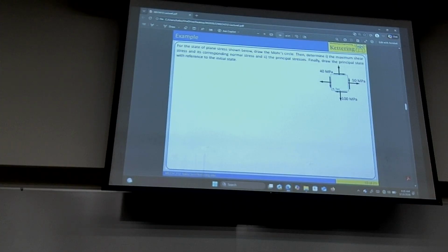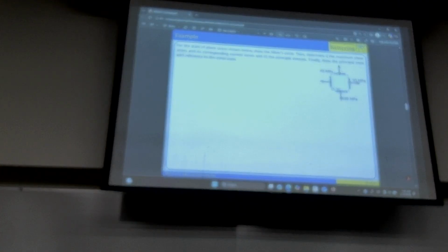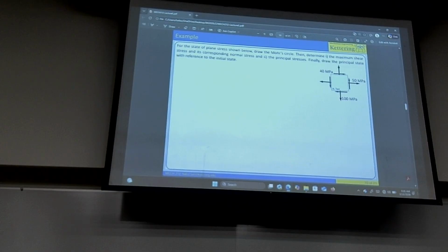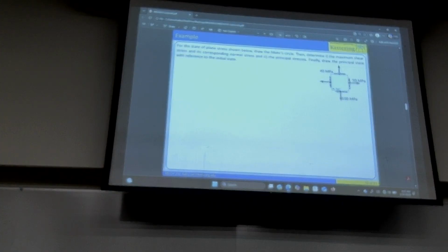And speaking of stress transformation that I just asked about, basically we said if we look at the garment as an application, we load it in X, Y, or we cause shear, what happens to a particular fiber? The fiber in a particular orientation. We know what we loaded. Guys, you open up your laptop and you're not paying attention. You're loading the garment in X, Y, and then with shear, what happens to a particular fiber, and then angle. That's why you would need to do stress transformation.